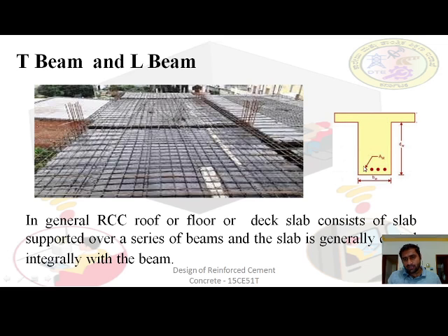So if the slab is constructed at the bottom level of the beam, actually the moments will be of the same nature and the slab will actually try to pull the beam, and the T-beam action nowhere exists. Actually you should design it as a beam. So in some cases this also will be happening. So inverted beam. So in some cases we will be constructing an inverted beam, where the slab will be casted at the bottom level.